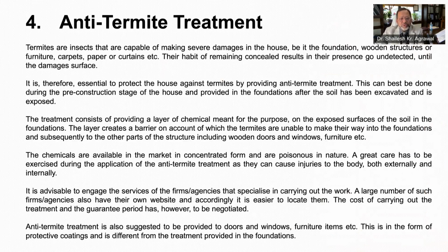However, these should be used with great care and following the procedures. Sometimes a separate agency may also be hired for anti-termite treatment. For doors and windows also, anti-termite treatment is suggested, in the form of protective coatings. This is all about specifications of foundations.